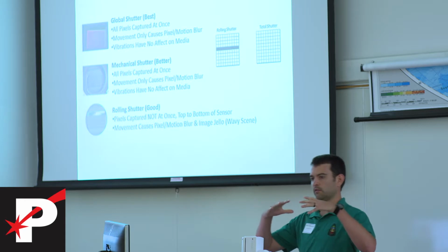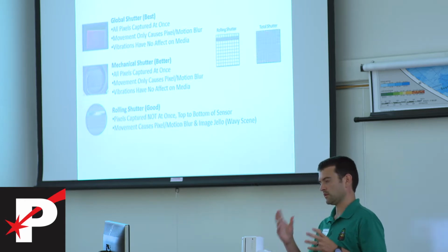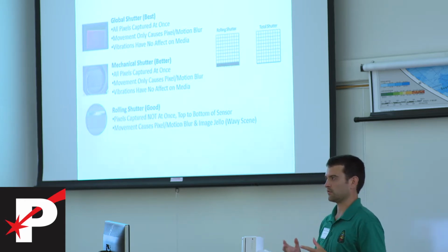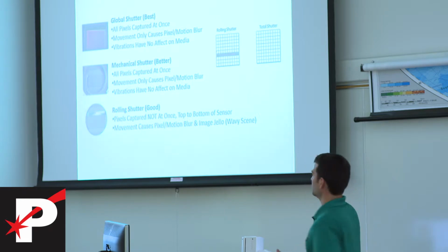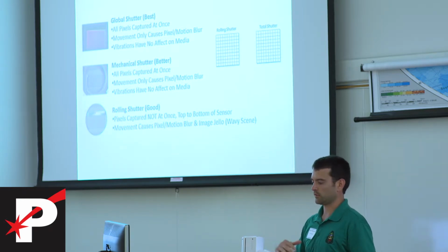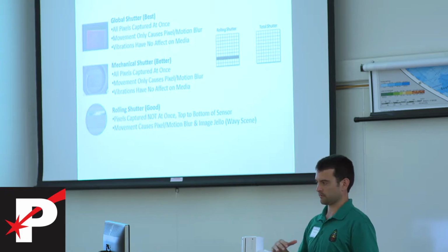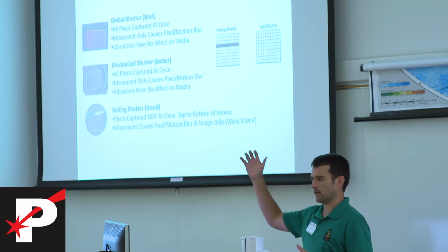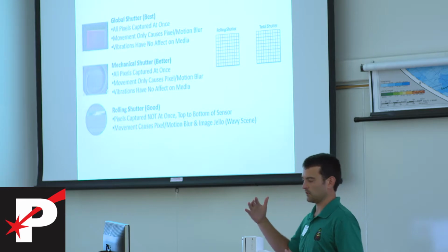They have a rolling shutter. In case you're curious, there's no 20 megapixel sensor that's global shutter that exists. Global shutters are very low volume, low production, very expensive, and very low resolution, but they're getting more and more high resolution as more of them are being manufactured.